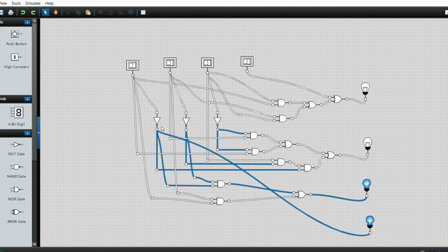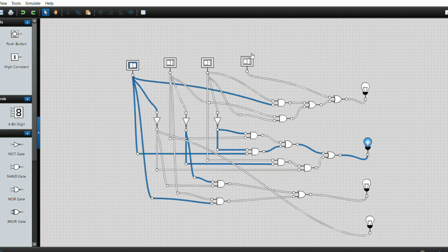So we have used 3 NOT gates and 5 OR gates, and the rest of them are AND gates, and it is used to convert the binary coded decimal to XS3. And now we will see another input, 1001. So for 1001, the output is 1100. So for 1001 in binary coded decimal, the XS3 output is 1100.